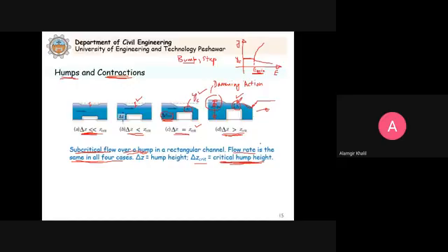This is the problem which we will discuss to further highlight this. Because if immediately after YC we again have the subcritical depth, then this is not possible, because there will then be no way of dissipating the energy. So we need to dissipate the energy. So this depth has to be supercritical, and then it passes through the critical depth and becomes a subcritical depth.